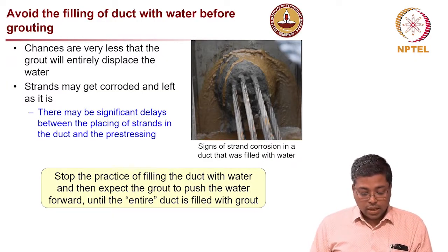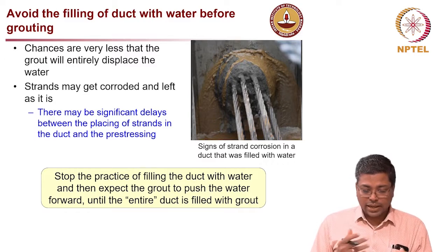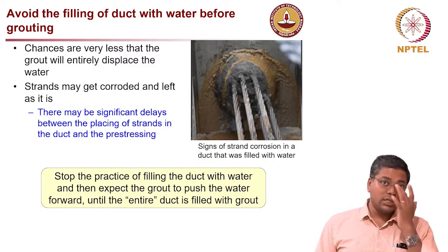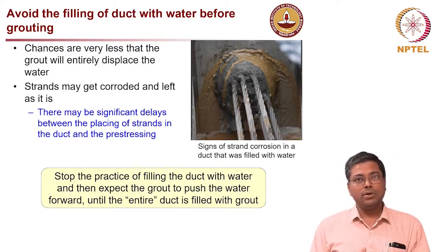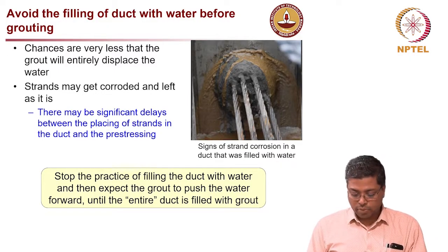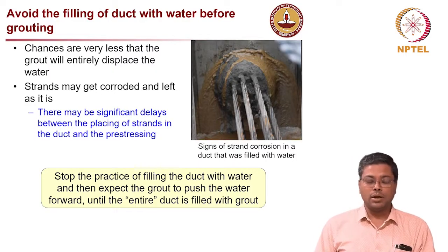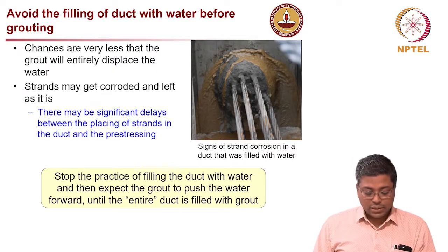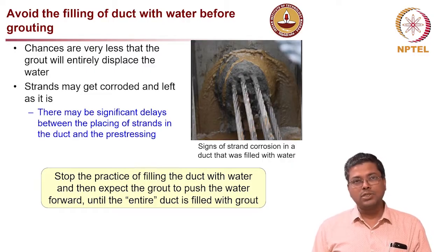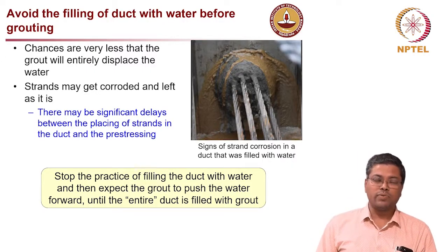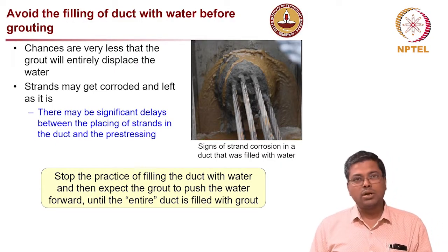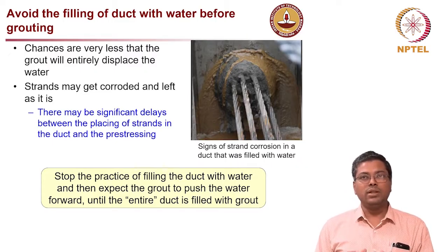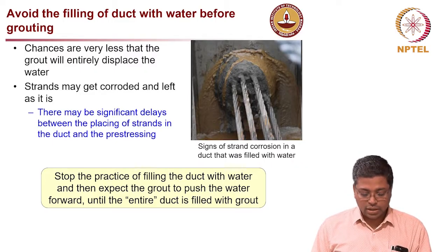Okay. Now there used to be a practice of filling the duct with water before the grout is filled in, expecting that the grout will displace the water and prevent the formation of air voids. This was the idea behind filling the duct with water. But it is not really a good idea, because the strands might get corroded, and if the water you use has a lot of chlorides, that might also affect them.